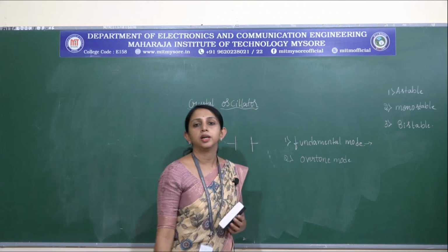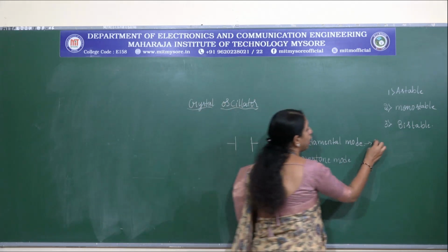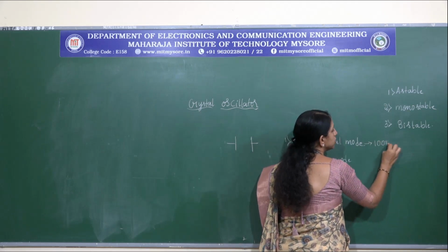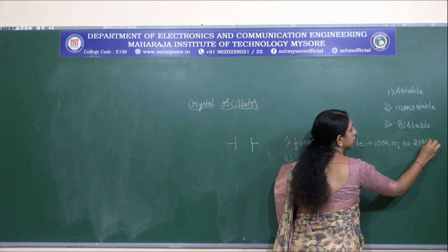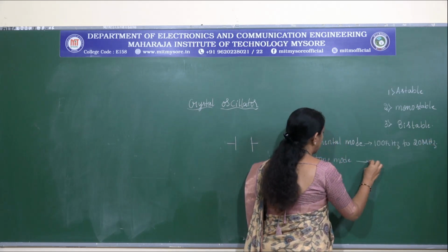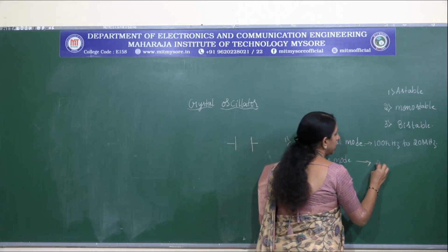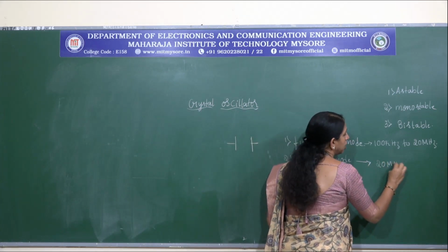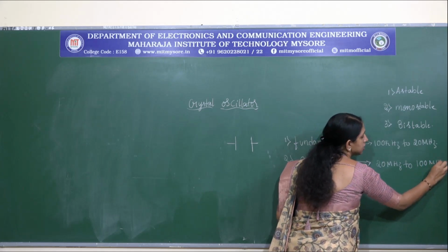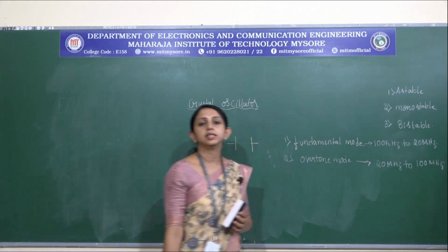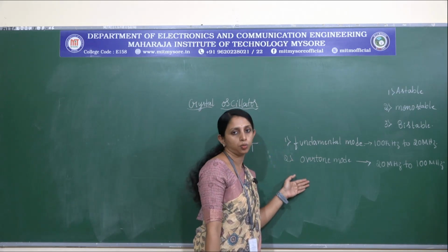In fundamental mode it works with a frequency range of 100 kilohertz to 20 megahertz, and in overtone mode it works from 20 megahertz to over 100 megahertz. So these are the frequency ranges of fundamental mode and overtone mode.